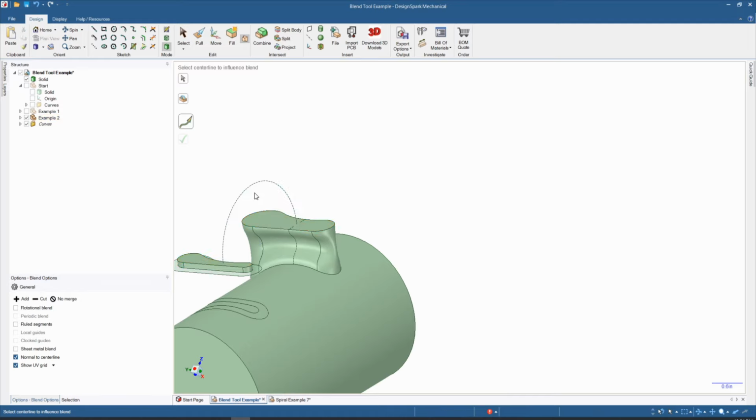And even if I escape out of this and I go back to my select tool and I select this edge and I control and select this edge, it will make the shape pull, but when I tell it I want it to go around a circle, it fails again because it doesn't know how to deal with this segment being curved, going around the arc and hitting a flat segment on the other side.